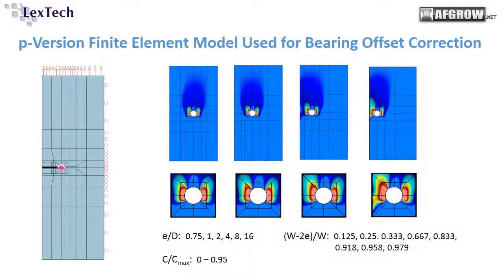As you see here too, what we had to do to make this closed form solution was to constrain one edge from bending in plane. If we didn't do that, it was almost impossible to obtain the closed form solution. But in real application, on an airframe, skins will be attached to stiffeners, and I think that the assumption that we have a constrained case is probably valid for most practical cases.